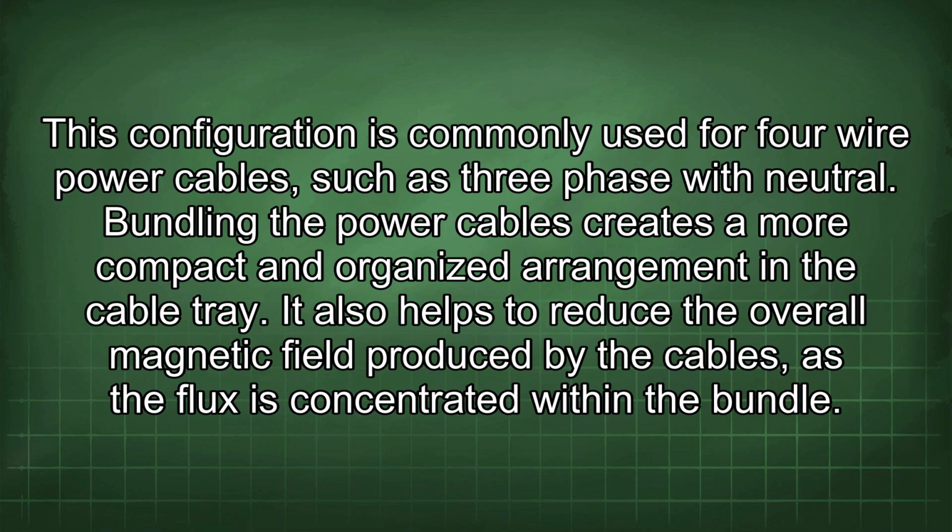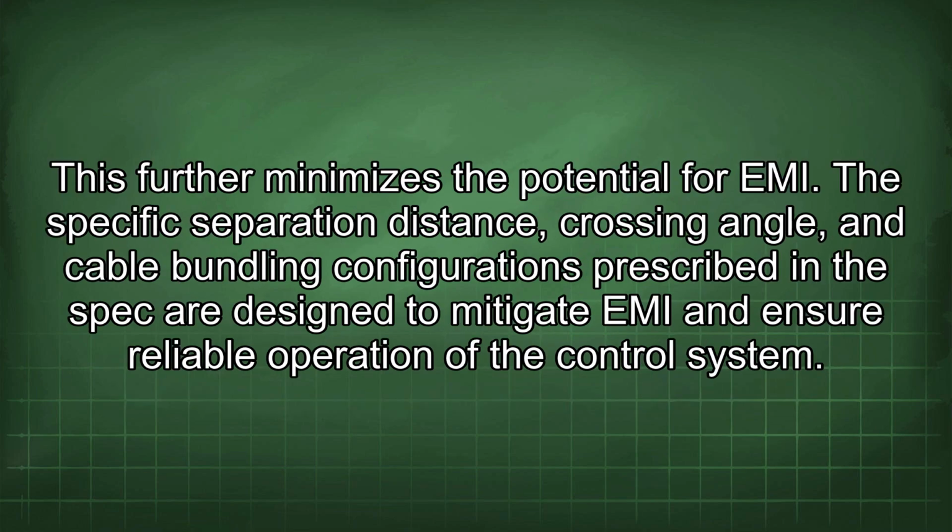Bundling the power cables creates a more compact and organized arrangement in the cable tray. It also helps to reduce the overall magnetic field produced by the cables, as the flux is concentrated within the bundle. This further minimizes the potential for EMI.